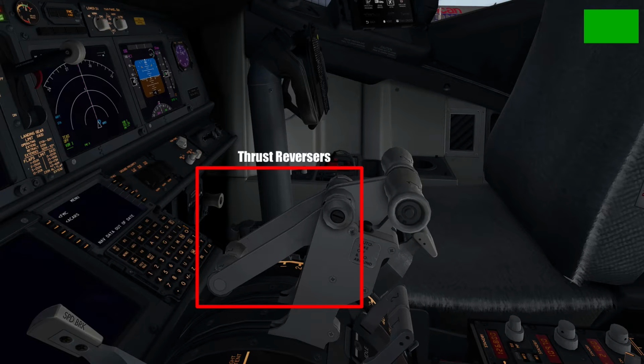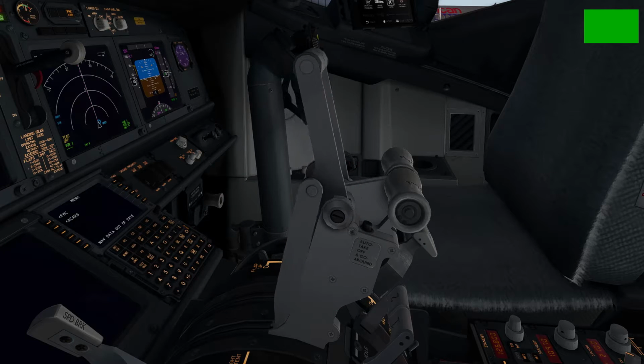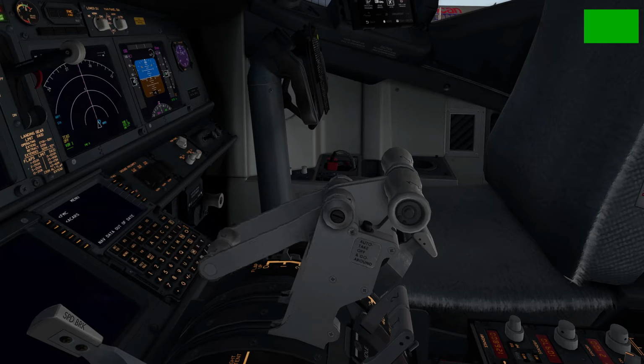This allows the aircraft to decelerate faster and, more importantly, takes some of the responsibility off of the brakes in the landing gear, which can get really hot if relied upon for the entire deceleration process. When these levers are simply lifted, the engines run at idle speed and therefore provide idle reverse thrust. However, pilots can manually pull these levers back to increase the deceleration by running the engines at a higher setting.